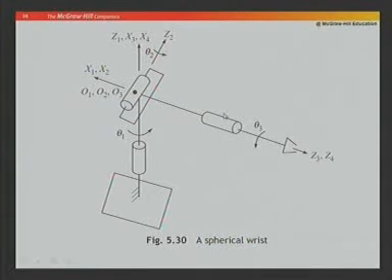This is perpendicular now, and again like before, one of the important points in finding DH parameters and doing the forward kinematics is to appropriately place the coordinate frames, and without good practice it will remain a very difficult and confusing task.